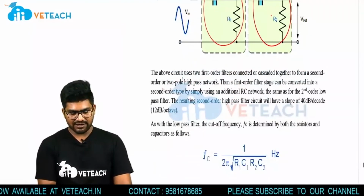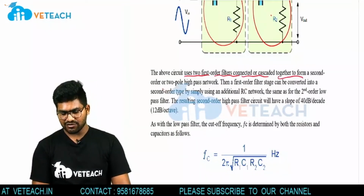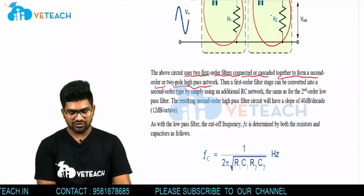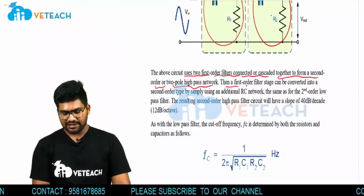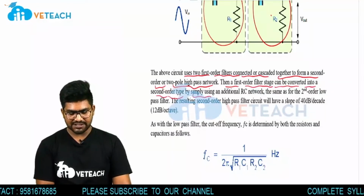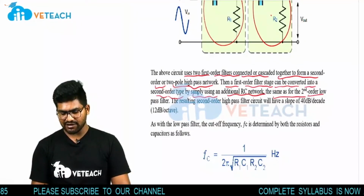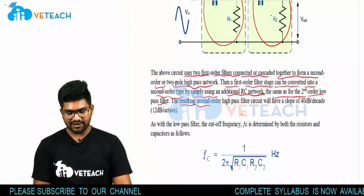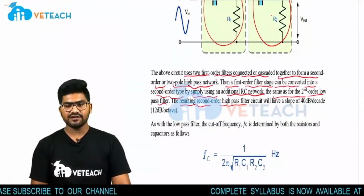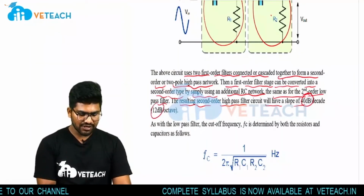The above circuit uses two first order filters cascaded together to form a second order or two pole high pass network. A first order filter stage can be converted into a second order type by simply using an additional RC network, the same as for the second order low pass filter. The resulting second order high pass filter circuit will have a slope of 40 dB per decade or 12 dB per octave.